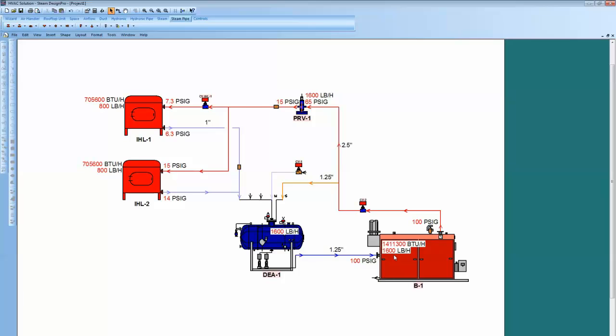That's what the boiler sees. Well, obviously I should come in here and come back to the steam toolbar and come grab an F&T trap and drop that on there. We need a trap after those autoclaves, right? That's an F&T trap. Spark circle F&T traps right there.